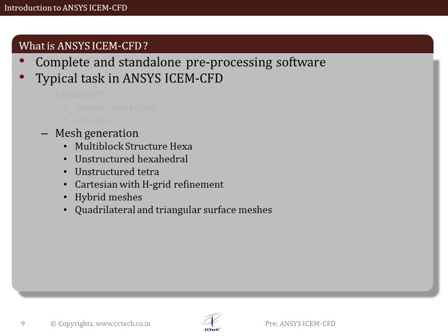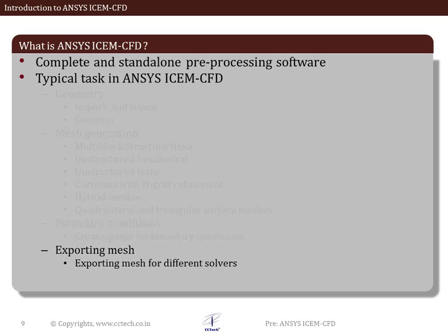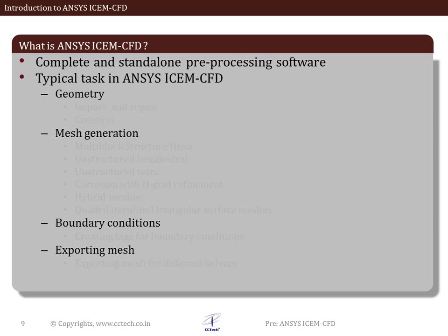It also includes either automatic or manual repair of generated grid. The boundary tagging is also done within ICEMCFD for easy solution setup. The grid is then exported in various solver formats. So to summarize, activities in ICEMCFD involve geometry creation, mesh generation, boundary taggings, and mesh export. Let's have a look at all these activities in detail.